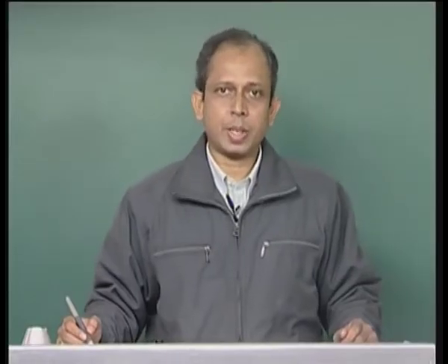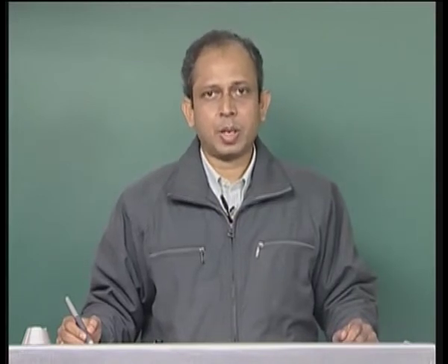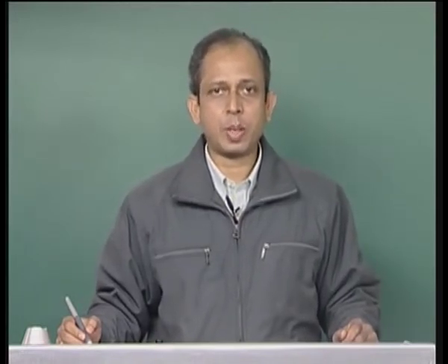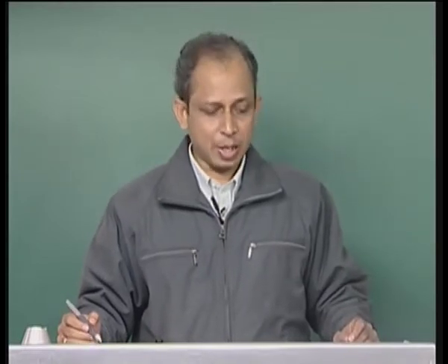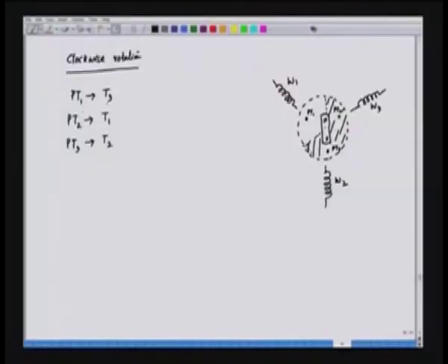So, we are just seeing the operation of a simple brushless DC motor. We have 3 windings in this case and we were discussing the clockwise rotation. In the clockwise rotation, the phototransistors will be connected like this, that PT1 will be connected to T3. So, in the present condition this is PT1, PT2 and PT3.